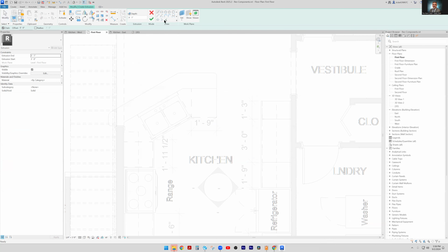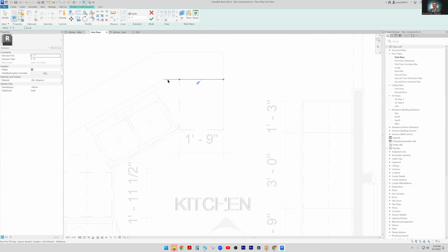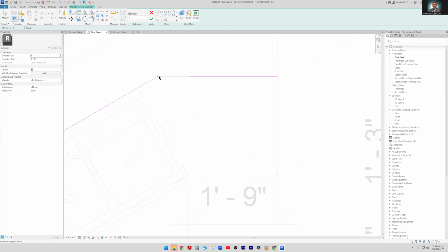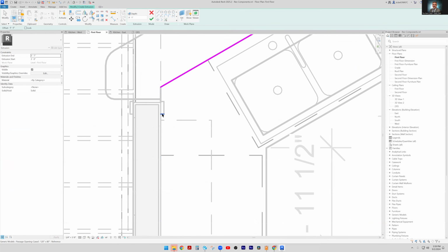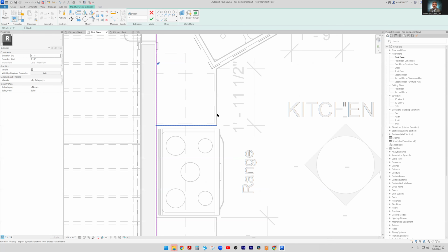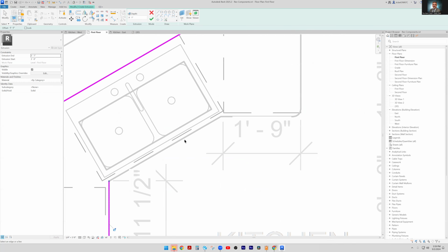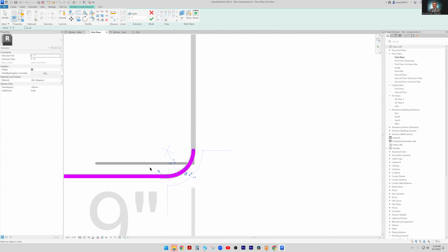Extrusion, do an outline pick line button. Seeing that the outline is already there for us, we'll just go ahead. And by the way, don't try to make that little gap between the two work out there, okay? Because that actually causes you headaches later. You want to make a single line if you can for every connecting line. All right, so right here, here, and here, here, and there's a little curve there. You can see the little concentric symbol. I'll turn that on and keep it and do this.